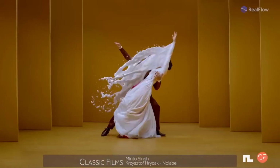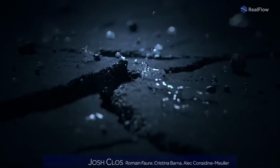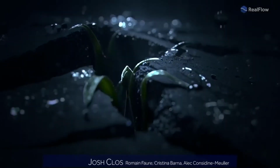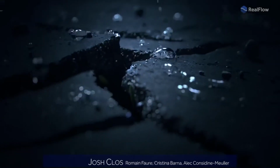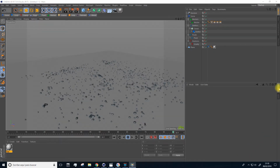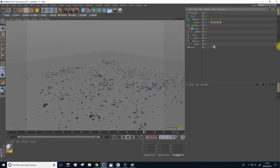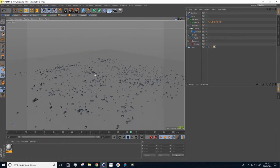Okay, so let's start with the first scene. Are you excited? Because I really am. Here we can see some raindrops falling on the ground and breaking. Creating this effect is quite simple. Just need to insert different emitters. We can even use the cloner to ease the task. Obviously, we would need a collider for the ground so that the drops collide with it.